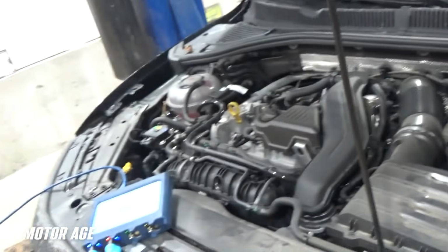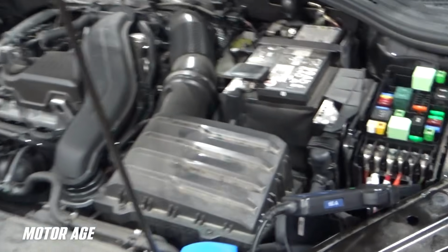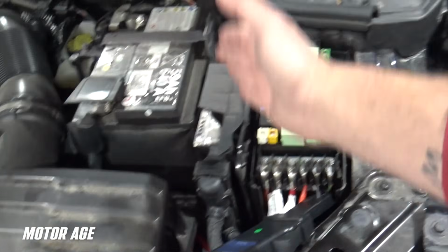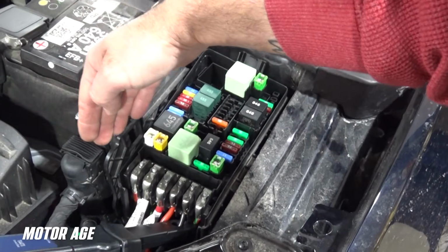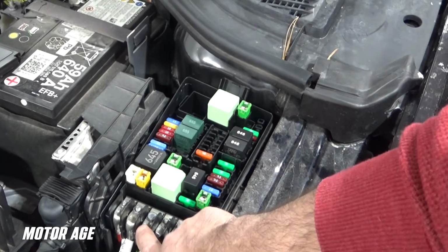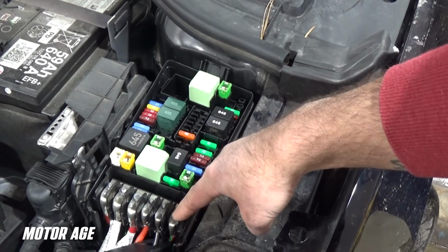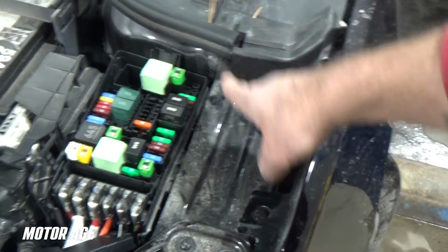And if you learn what tools can do and can't do and learn to leverage them properly, they could save you a lot of time, just as we did here. This 2025 Volkswagen with an intermittent parasitic drain could have been anywhere in this car. But using our tools and using our head, dividing and conquering. Rather than looking at the whole car, we went right here and figured out preliminarily which of these 5 circuits, yes, there's 6 here, one's an input, which of these 5 circuits houses the fault. Once we eliminated it down to one of the 5, we simply followed that, leveraging service information. It's as simple as that.